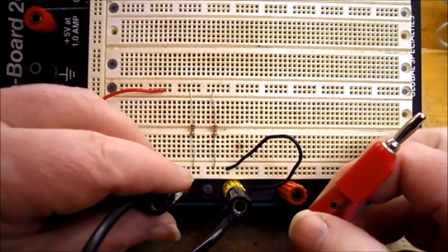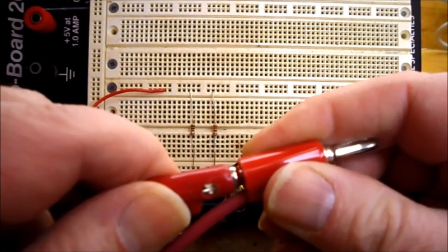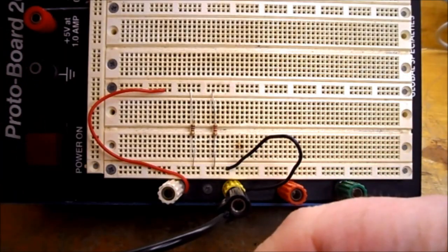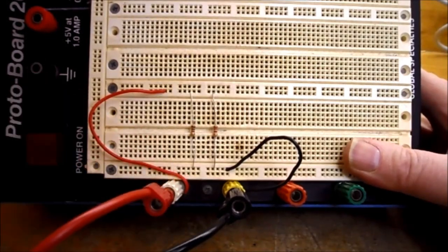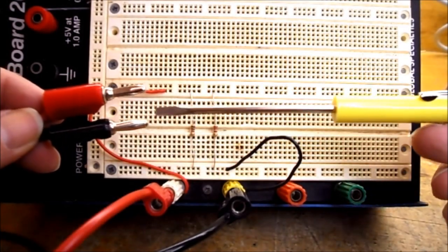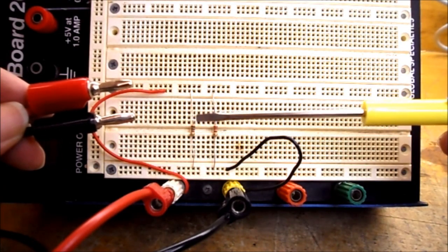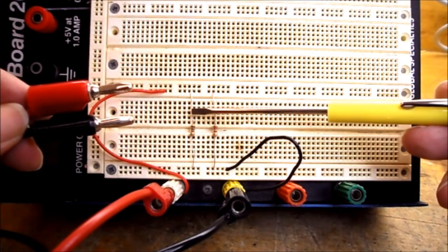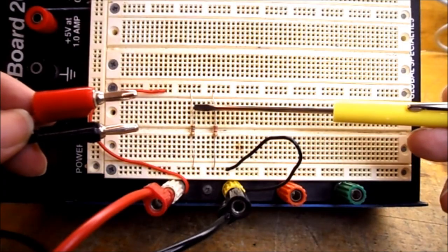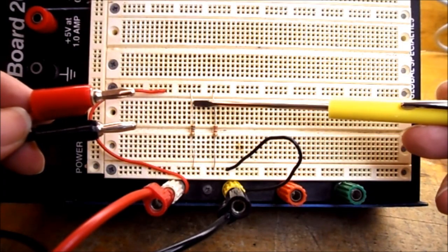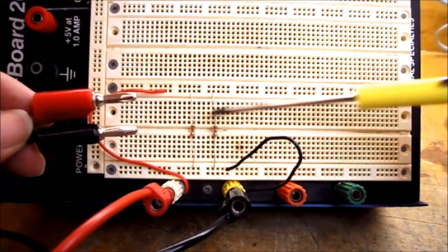So I have to disconnect the black lead from the ammeter, and I have to disconnect the red lead from the ammeter, and then I have to put the red lead from the power supply back into my circuit. So these are the 2 leads from my ammeter, and remember, to measure a current through a circuit, I have to break a circuit. So I want to measure the current going through R1, which is a 1 k ohm resistor. So in order to do that, I need to break the path that the current goes through on the 1 k ohm resistor.